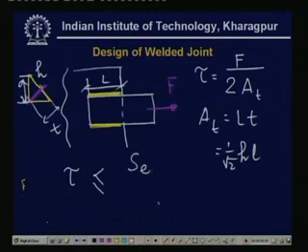Here the endurance limit is to be calculated for shear stress, because now the loading is of shear type.